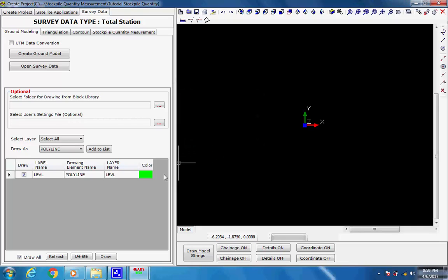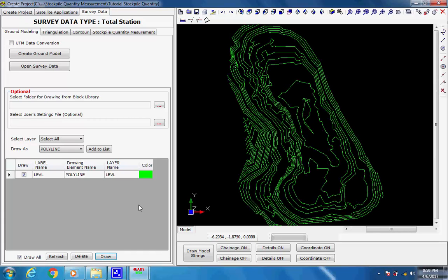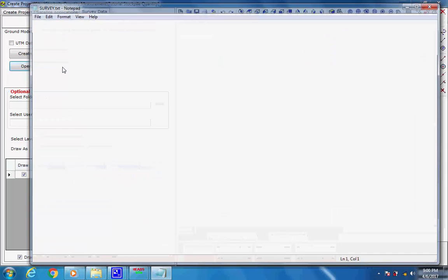The user can remove the check mark from a feature, if we want to deselect the feature, to exclude it from the drawing of the ground model. Next, click on button Draw at the bottom of the left panel of the workspace. By digital mapping, the features are drawn with the selected color. On the right side CAD window, we can save the drawing of the ground model either as DWG or DXF, but in the unauthorized version any saving of drawing file is not possible.